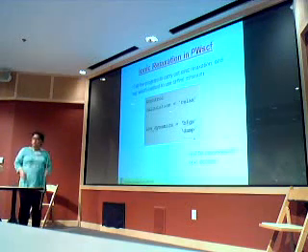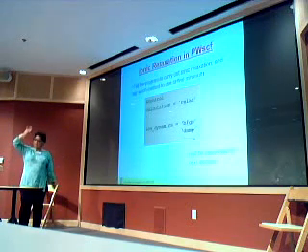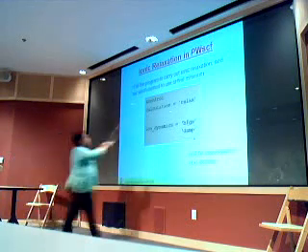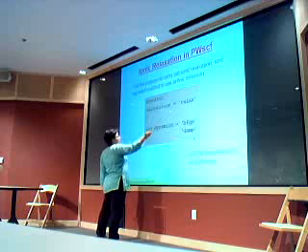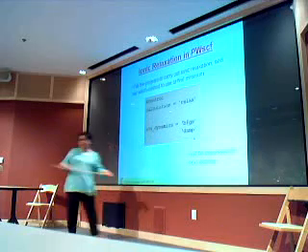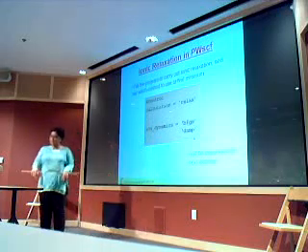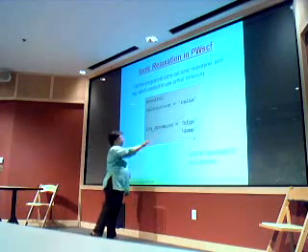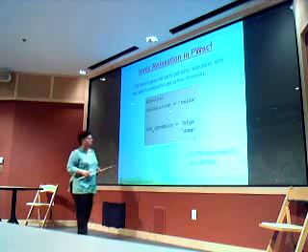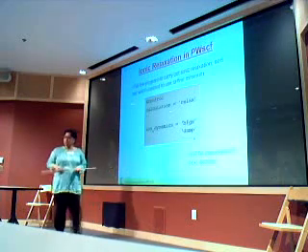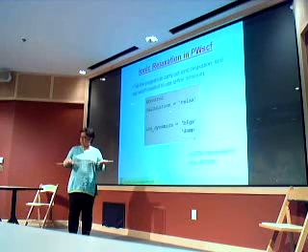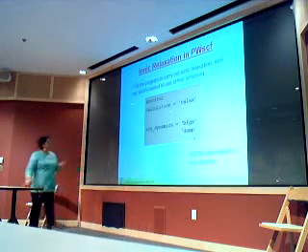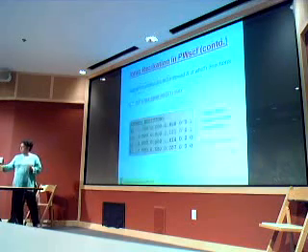So to do this in PWSCF, yesterday in the very first namelist, the control card, we had said calculation equals scf. Now instead you put calculation equals relax. And you can use the BFGS algorithm for finding the minimum. Or you can also use what is called damped dynamics. And I won't discuss that, but Stefano will discuss that in the next lecture.